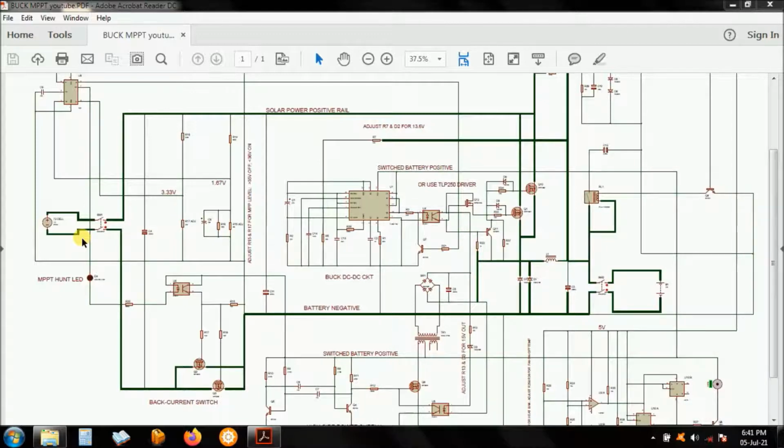They are now cheaper than smaller modules, which are 50 watts, 100 watts. So you can have a 350, 360, 400 watt solar module charging a 12 volt battery. That is now possible with the solar charge controller, which has got a power supply. The maximum power point tracking feature is mostly an added feature to charge controllers, and it's only for the purpose of efficient harvesting of energy.